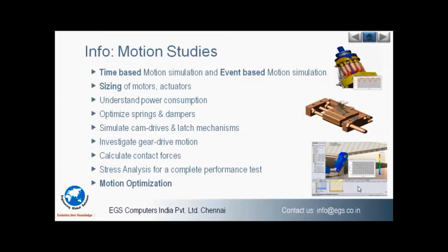Using the motion study, we can study how many motors or how many actuators I need to keep, and you can even size the motors and the actuators. By this, we are going to understand the power consumption for our assemblies. And for those of you dealing with springs and dampers, we have an option to directly access the springs and the dampers inside the kinematics, and we can even optimize these springs.